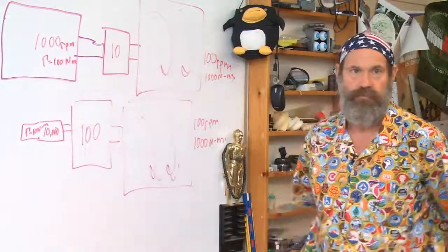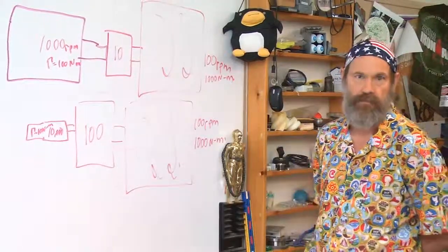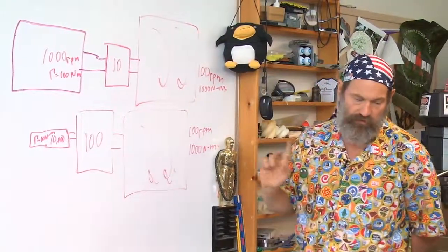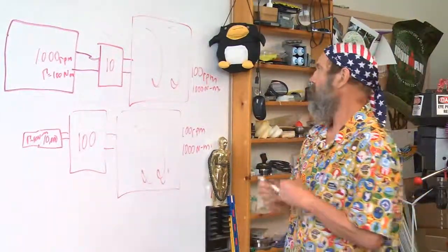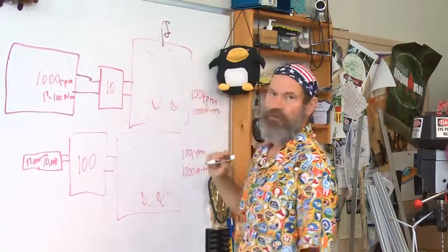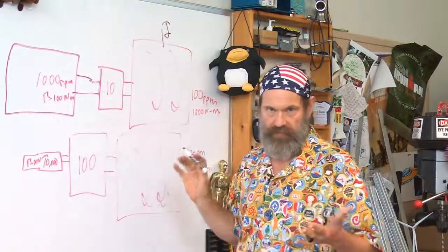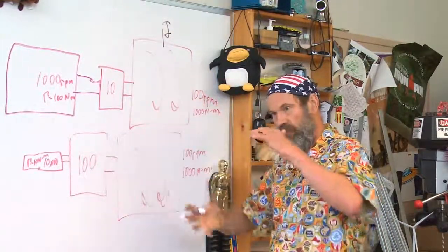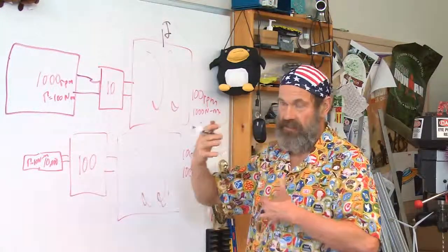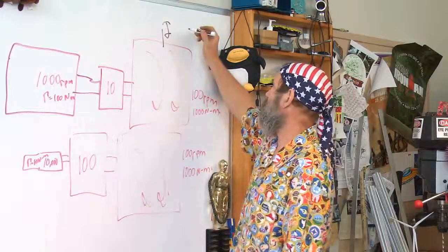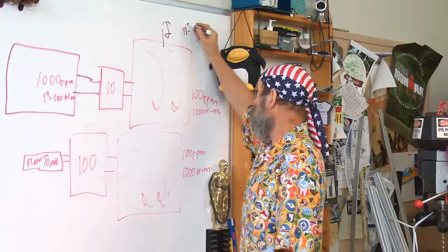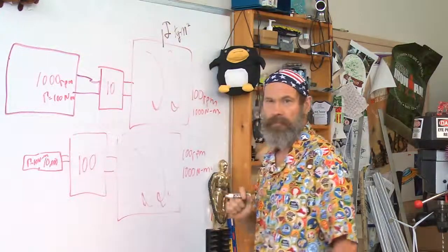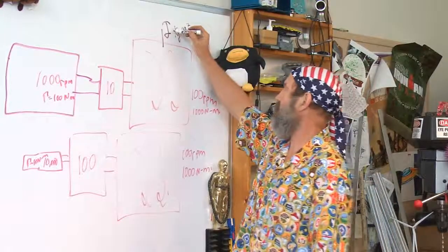So which one do I do? Which one will cost me less? You see, the math actually works out very nicely. You start with understanding what is the inertia of your load. So go back and review your basic intro to physics about what the inertia is. But the rotary inertia is analogous to the mass. And it'll have units of kilogram meters squared. Okay?